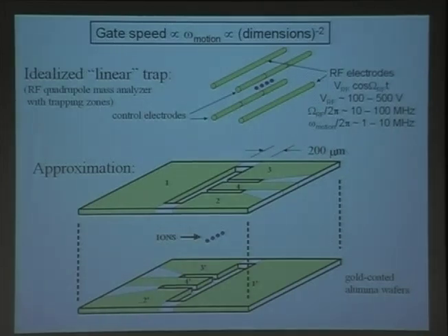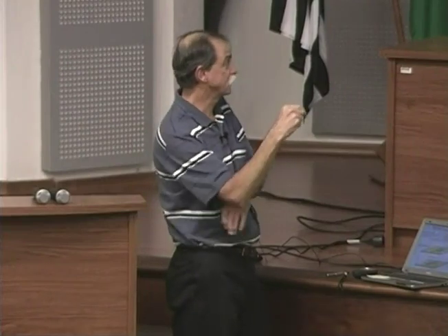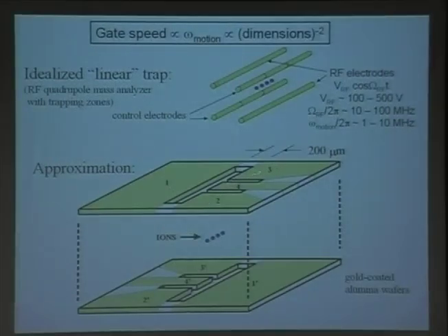One way we've been able to make these structures, certainly not the only way and not the best way in the end, we think, but we've been able to do quite a few experiments approximating this structure, is to take alumina plates, alumina being a good insulator, and gold coat these alumina plates in a way that mimics the structure here. For example, the internal surface of this electrode we mimic with that surface there, and then the cuts in these electrodes we laser machine as slots in the alumina substrates and then divide the electrodes as I've shown here.